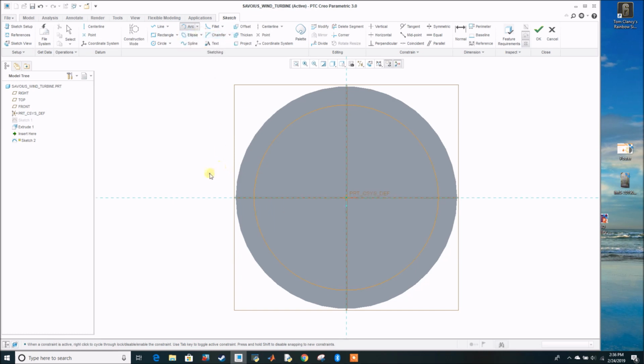Now choose the end point, choose any other point like this, and select the center on this line. This has been selected as a radius of 78. We have to select 75 radius, so we will select 75, enter. Now this blade arc is 75 of radius.